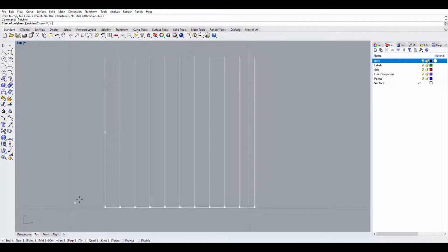So if you're having difficulty trying to snap to an edge or a midpoint or something like that, look down here and make sure you have some of those selected or not selected. Another useful tool is Gumball. A lot of times Gumball is not turned on.